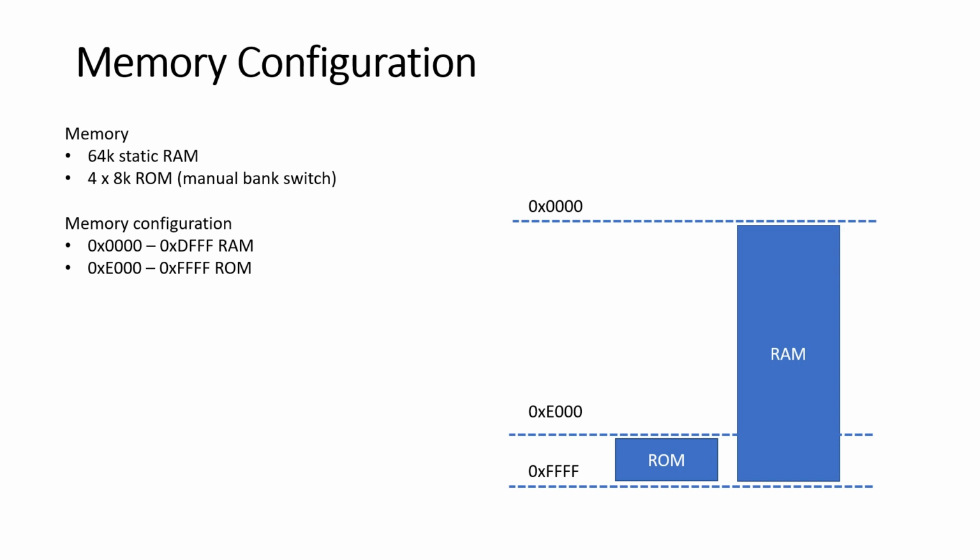So a program can only access an amount of 56K of RAM, but the stack area is placed underneath the ROM area, so that whenever the stack is accessed, the ROM is unavailable and the CPU grabs from the remaining RAM that is behind the E000 area.